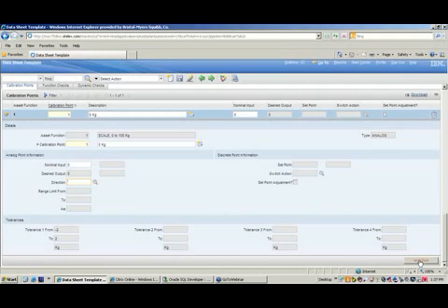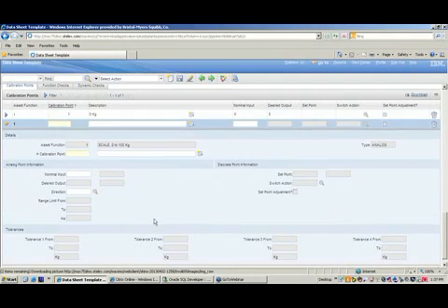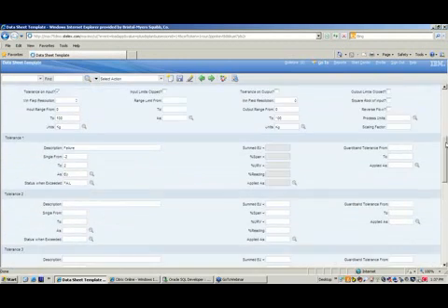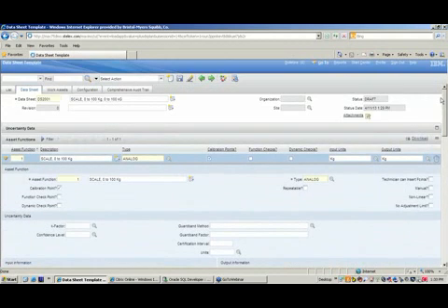You can keep building our definition for tolerance or calibration points, adding as many as possible. Again, if we continue, we may add a third at this point, and we'll go to full scale. Okay. So again, adding your calibration points is defined according to either OEM specs or your metrology, whatever defines the calibration necessary. At that time, you basically save the record.